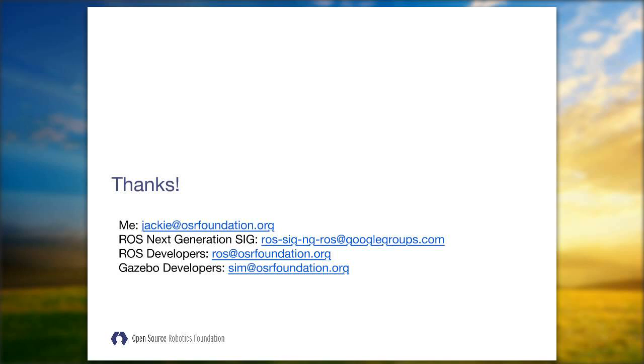There's one last question: does Gazebo allow the robot model to change at runtime in terms of adding and removing links? Yeah, but it's difficult, is the answer I give a lot of people. You could write a plugin and use the physics interface to dynamically add and remove links to your model, but it might have weird effects on physics. We do this for the model editor and a couple of other tools. There's not a dynamic way of doing it through the GUI besides using the model editor. Okay, thanks a lot.